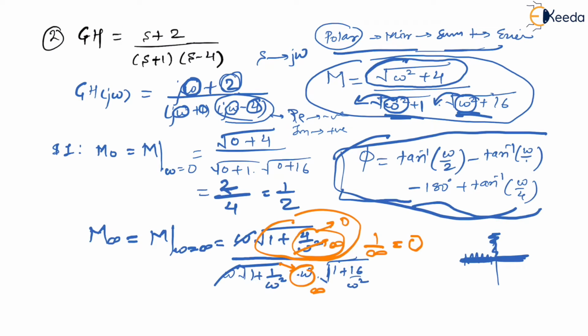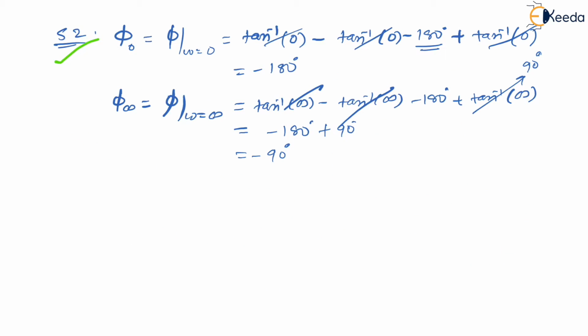Now if you observe what you have, it has to be the observation at first. If you see, you are having one pole on the right half of S plane, right? This means that the four step method cannot be applied completely, right? But step 1 and step 2 can be done. So yes, step 1 and step 2 have been done. But now we are interested in what is the exact plot for this. Okay, so let us start. So if you check out, we will be having four possibilities, right? Let us check them.